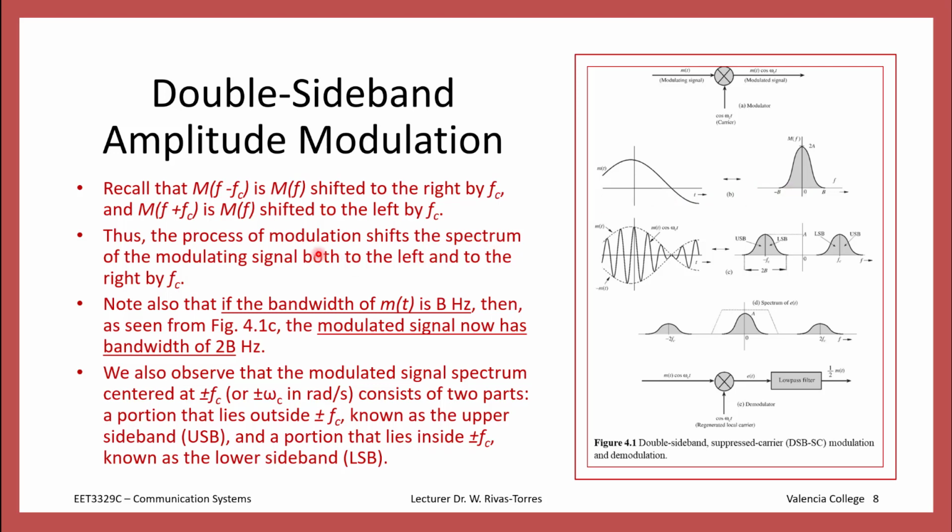Now, when you modulate the signal as a double sideband signal, you are going to take this response. Remember, we look at the response around zero, but what we're really interested in is what happens at zero and above. The reason we show it like this, as I explained before, is that it is mathematically correct. The mathematics make us do this. When you do the Fourier transform, you end up with the same signal mirrored on the negative side.